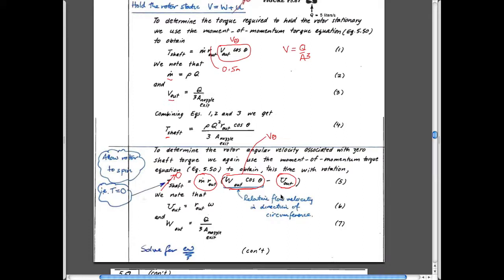to each other. And so it's not so different from the gas cylinder calculation in that the velocity of the sprinkler head that it moves at has to be exactly the same as the component of water squirting tangential to the circle of rotation. For the case of the decapitated cylinder, the velocity it moves at is the same velocity as the stuff squirting out the back.